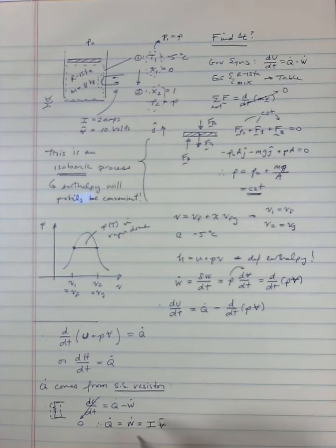This is the work rate, and this is the Q. This Q right here is the Q that's going out, so to speak. So Q is positive in. In this case, the work rate better be negative since I'm putting work in. So we want this to be a minus, right? So we're putting work in. We're putting the work of the power plant into the resistor, and it's heating it up, and then I'm getting heat transfer out. So this better be less than 0 to start off with, and that's why this negative sign